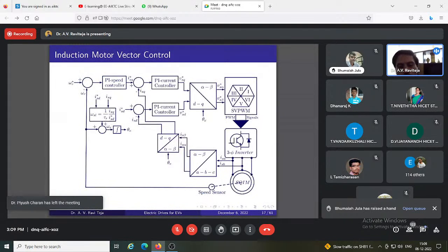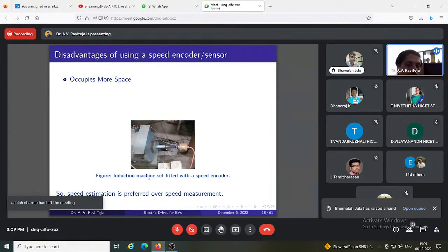Okay, so in this again, if I am doing speed control and you are sensing the speed, you can remove the speed sensor further, because mechanical sensors are mainly the first thing to create trouble in the system. Why? Because they are mechanically connected with the motor shaft as shown in this figure, and you have to take wire and signals from the sensor to the controller, and using this long wire you may have noise issues, as well as they may pick up noise or get distorted, and then based on that you have to work.